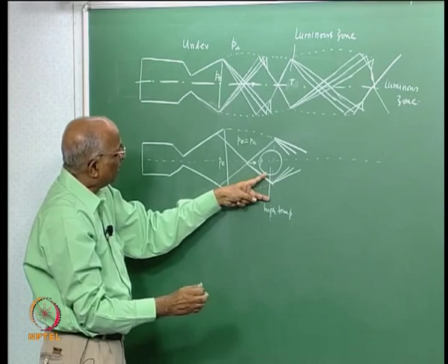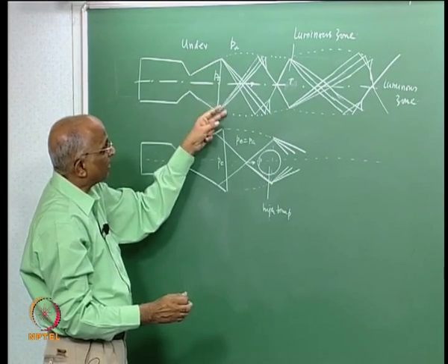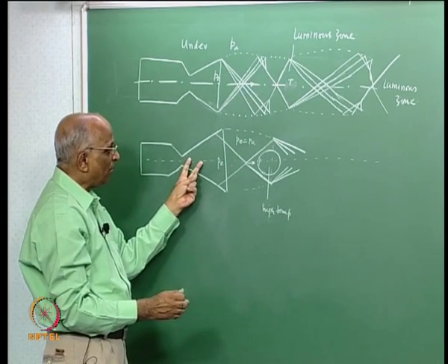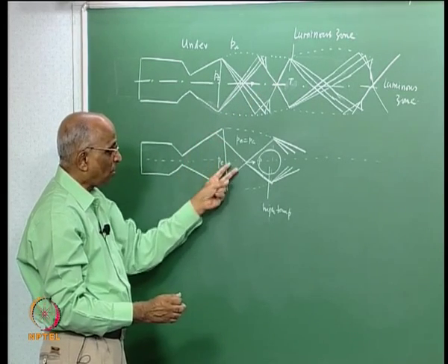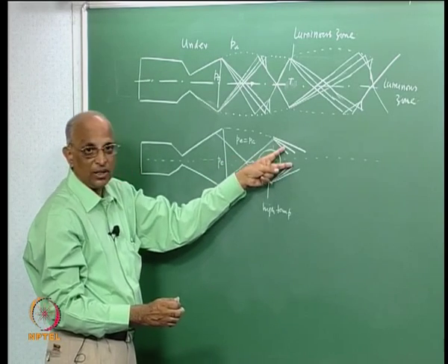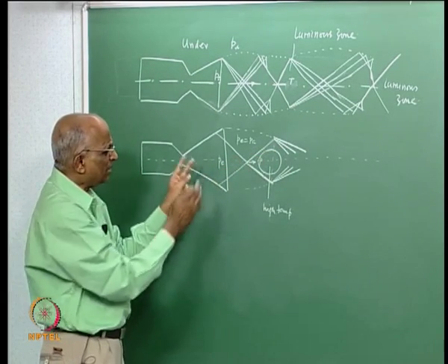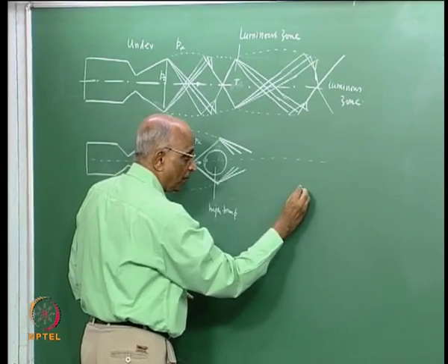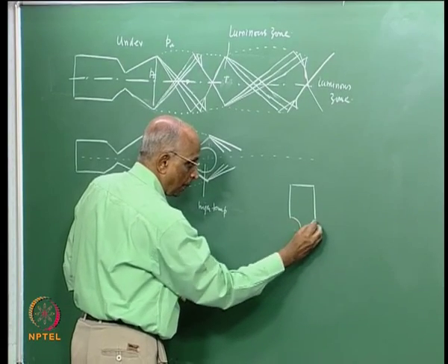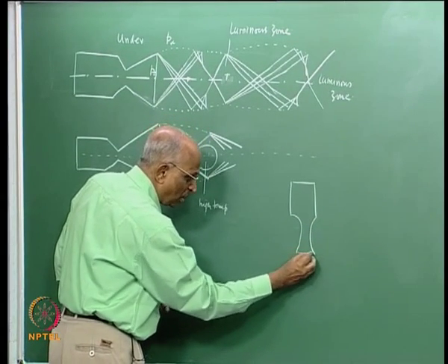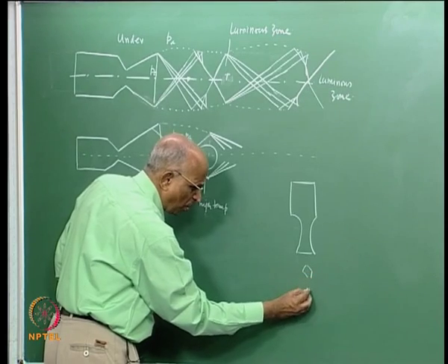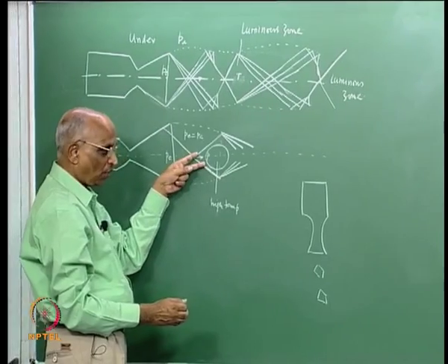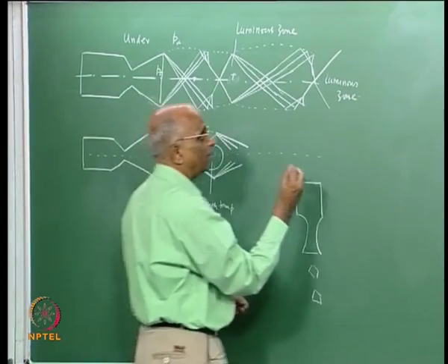Therefore, what is happening in an under expanded nozzle, I have a set of initial rarefaction fans followed by oblique shock waves. In the case of an over expanded nozzle, I have oblique shock waves which thereafter result in expansion fans. Therefore, there is a distinct change in the plume if I consider a rocket moving up. If the expansion is not there, maybe I should get some bright spots, and these bright spots are due to the shock wave, and these are known as shock diamonds.